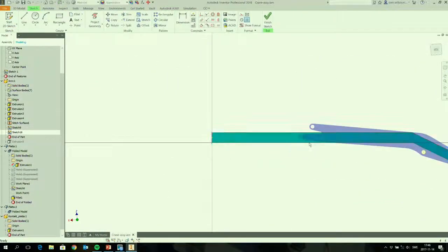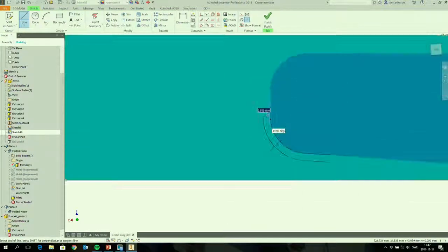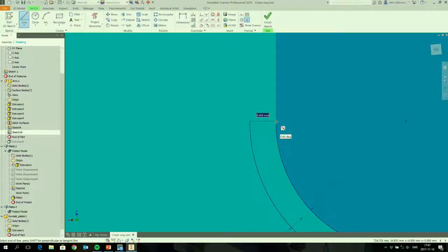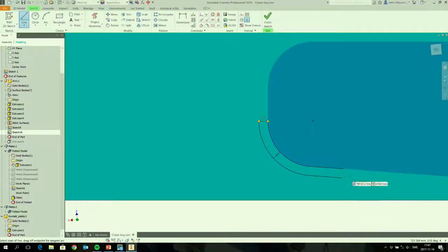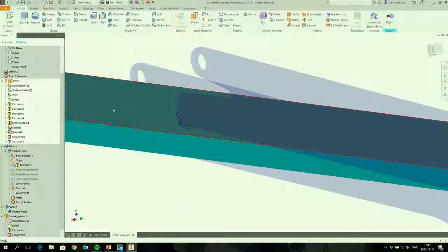So I create the CAD sketch. I project this line. I add a little line in this direction. It's not important how it looks. I end it. I make a little bit of offset. So I make this one, let's make it 4 millimeters. It's not very exact. The reason I choose 4 is that the weld root will probably be about that. Probably we will have a weld size of 3 millimeters, and that makes the weld root come about 4 millimeters out. So I want to be able to look at the stresses at this position. So I make it like that.